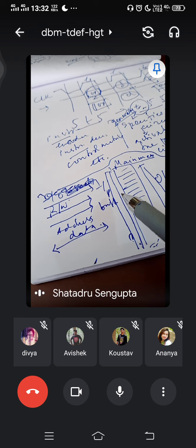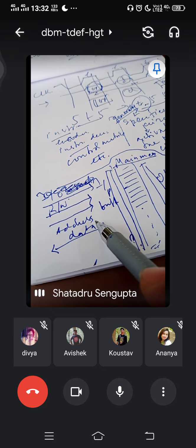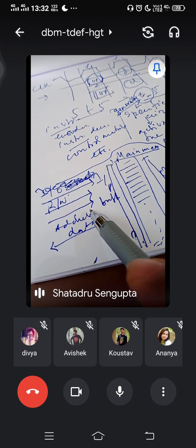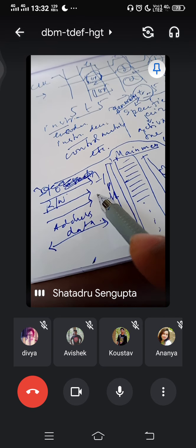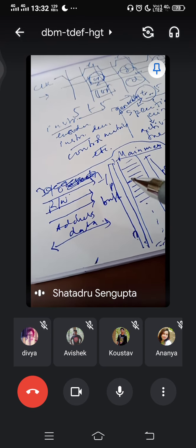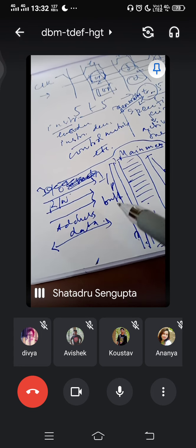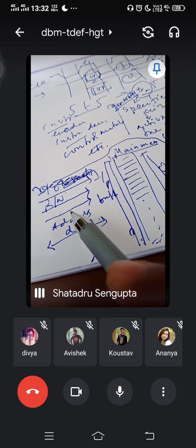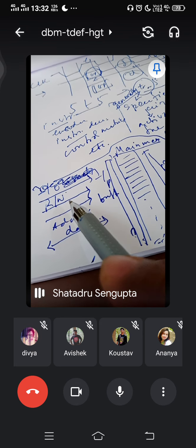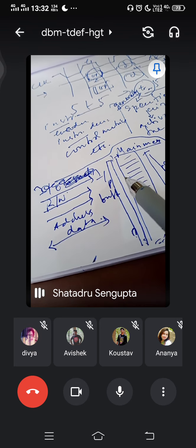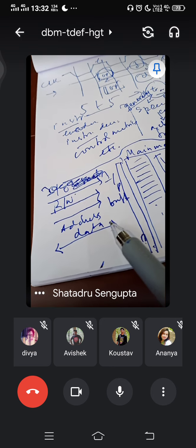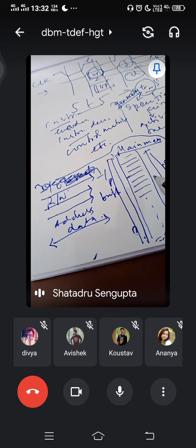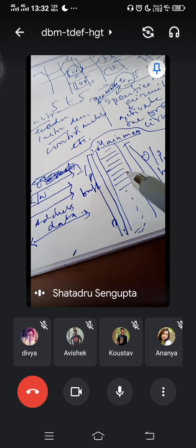And in all of these, if you're writing and you arrive with the data, but the address is not selected and the read write signal is not selected, what will happen? Obviously, the data will be lost. Only after you select the address and put it to read or write, then when you come with the data it will make sense, or then only you can read something meaningfully from the memory.